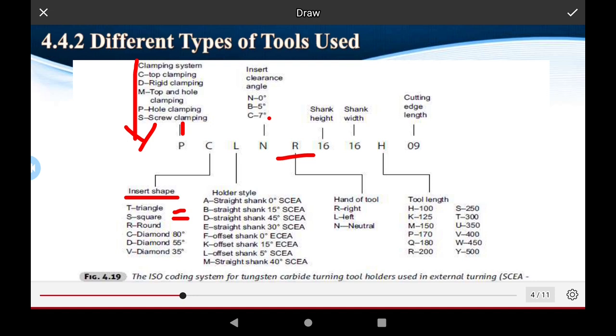Left hand, where the work is performed on the left-hand side, is given by the command L, and right is for the operation on the right-hand side of the CNC machine tool, given by the machine command R. The neutral axis is the axis for cutting the job, and it is given by N.